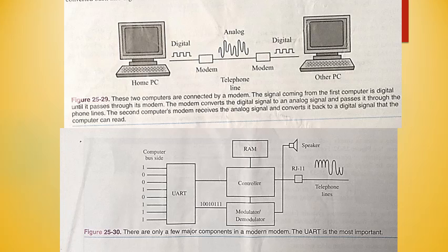Long spans of telephone networks are in fact digital. To be completely accurate, the digital signal in the PC is first converted to an analog signal. The analog signal is then converted back to digital before it encounters the telephone switching gear located at the telephone company's hardware. The digital signal is transmitted across the vast distances and then converted back to an analog signal when it is near its destination. At the destination computer, the modem converts the analog encoded signal to a digital signal.